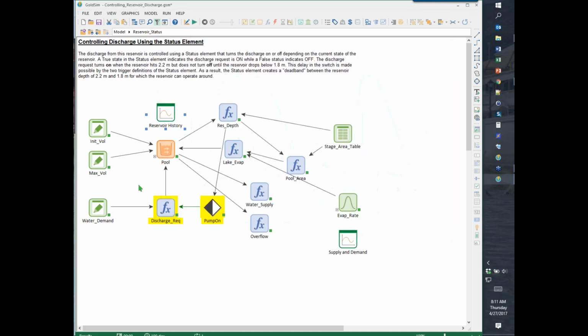Okay, so all of these options are great, and they work especially well when your residence time in your storage element is large, in particular, larger than your time step. But what happens if your storage elements are small? This is a case that you run into when you're simulating process flows in a system where you have relatively smaller tanks.